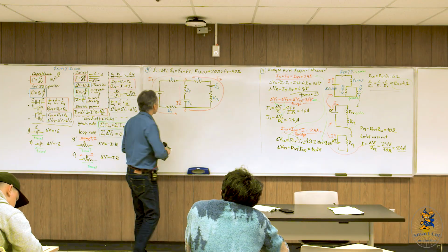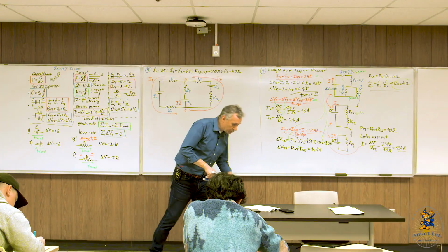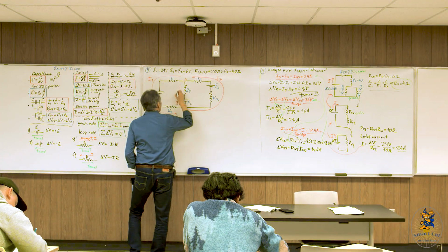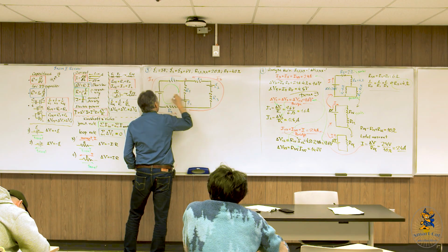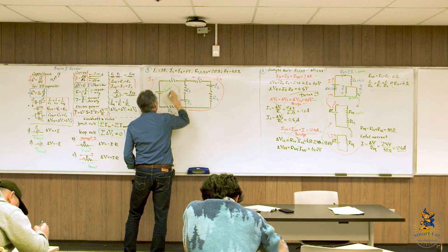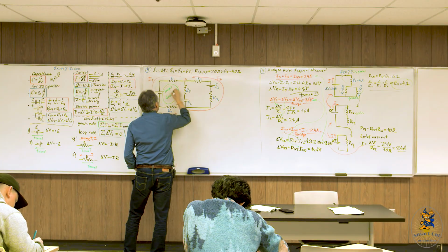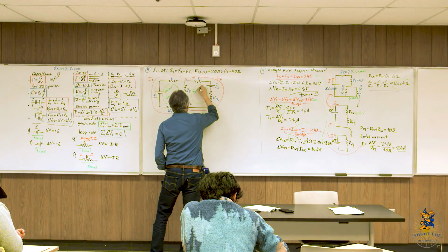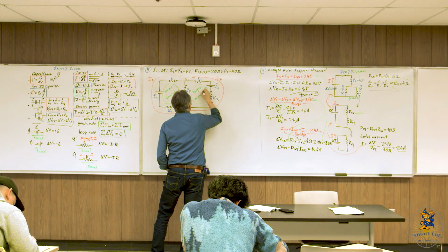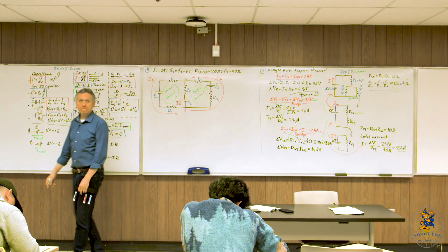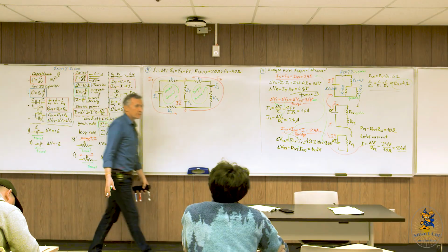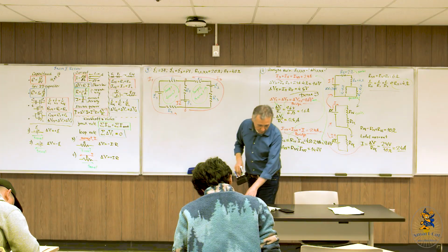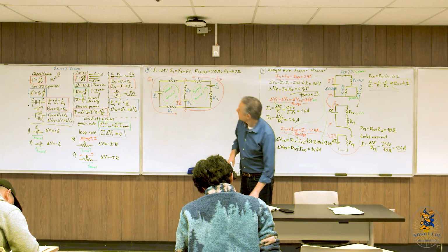And the last step which we need to introduce before we start writing down the equations is travel directions. Again, it's up to you which directions to use. In this case, I picked counterclockwise. I don't know why I used counterclockwise. So loop 1, travel. And I think the same here. So loop 2, that's the travel direction. Now all the preliminary steps are done, so now we can start writing down the equations.